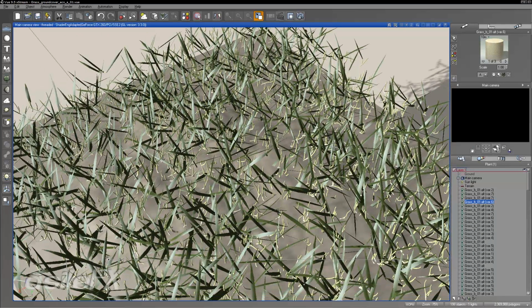This is also a cool way to find out exactly how many variations of each ecosystem species are created when you generate an ecosystem. With this species, the lily of the valley, the original source species, there are 8 variations or 8 objects that are created when you populate an ecosystem. Those 8 copies are then oriented in different ways and scaled in different ways in order to create more variations, but the base geometry is 8 variations, so 8 objects.